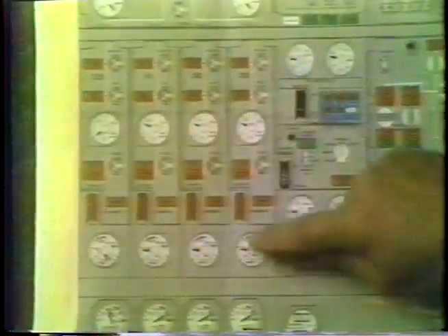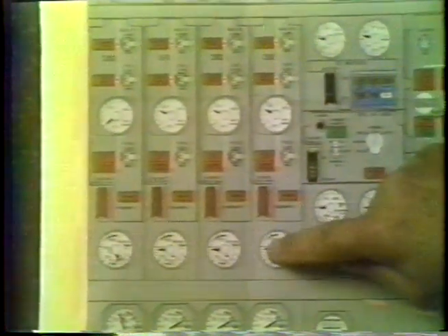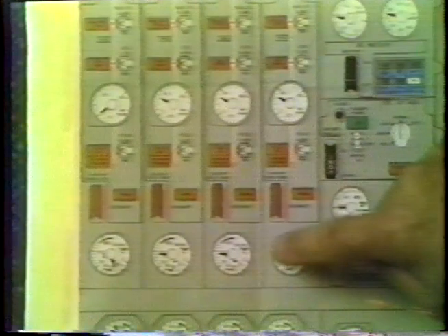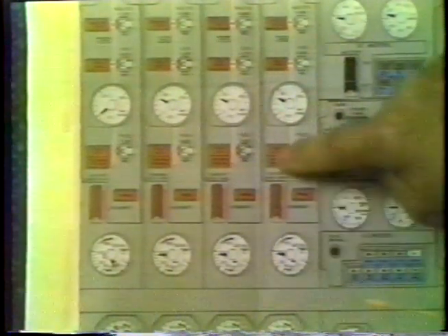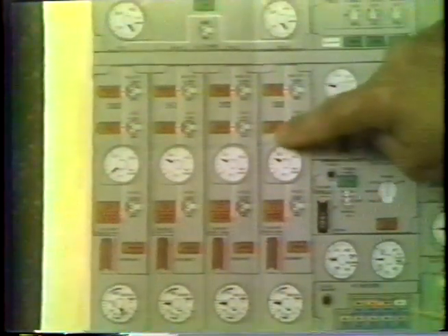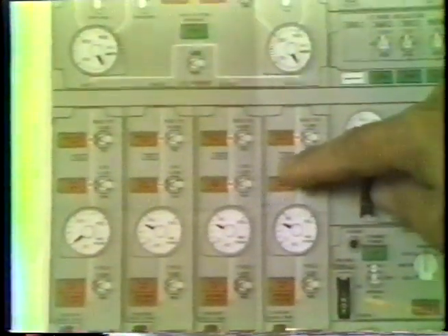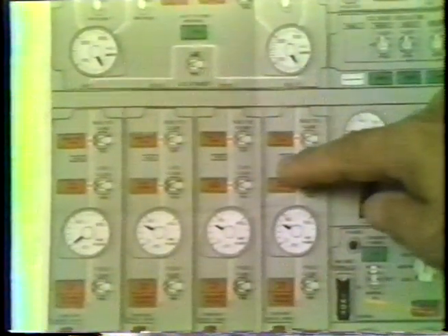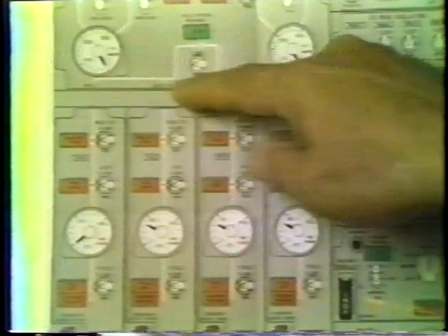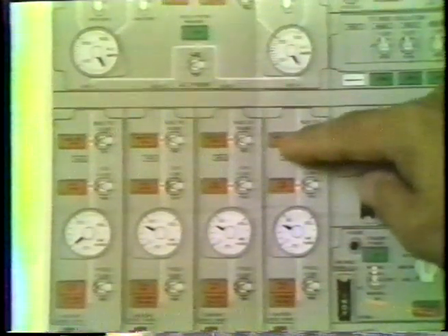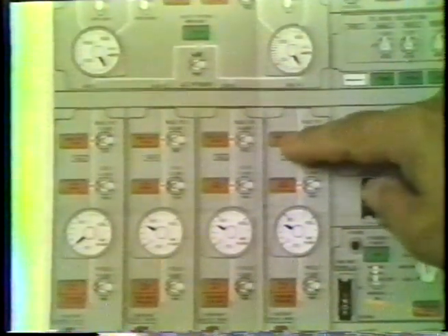The flow of power is very nicely laid out by a Boeing schematic here of each of the 4 main AC buses on the airplane. The engine drives the CSD, which operates the generator, which goes through a meter, through a generator breaker switch to supply power to an AC bus. The AC bus can also be supplied through a tie bus from any of the other operating generators, or APU, or ground power.